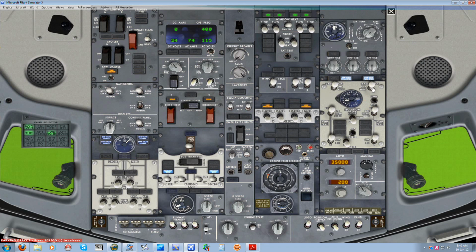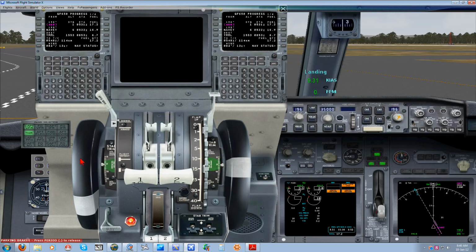Okay, once that's off, you'll actually hear the air conditioning system shut down, and all we need to do then is come down to our right engine start switch. You've got engine 1, engine 2. Leave the engine start switch on both, and the actual start switch here, we move that to ground. Okay, to GRD, ground. Then we just come back to our throttle quadrant.